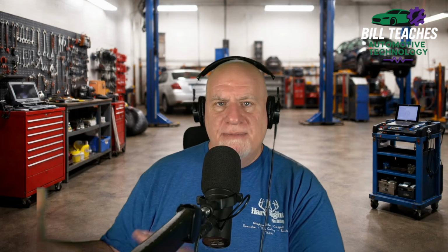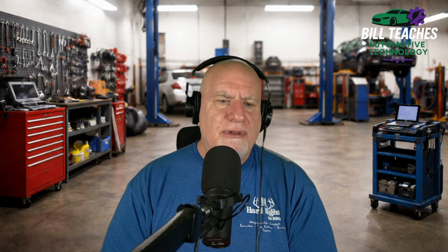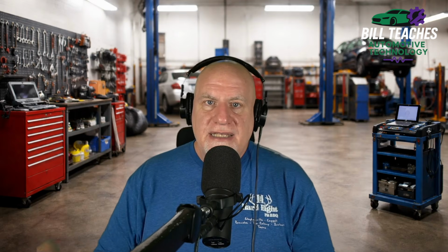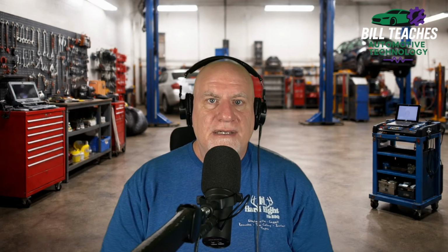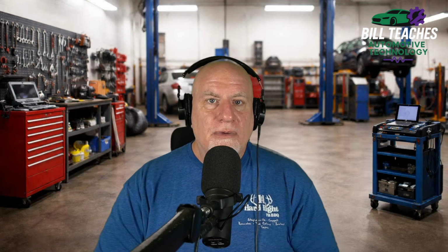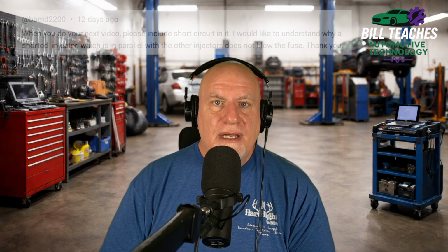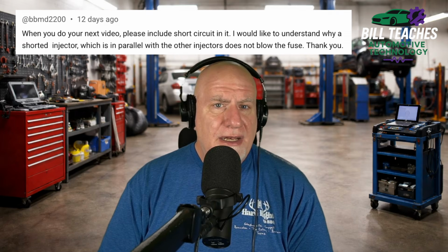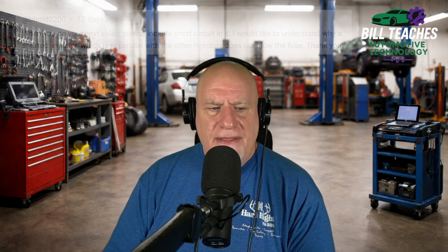But to help explain this, let's look at a simple injector circuit and walk through the different circuit failure possibilities. So today's lesson is going to be about opens, shorts to power, shorts to ground, and how a circuit normally operates. I had a viewer ask the question, why, when an electrical component like an injector fails, does it not blow the fuse? And that gave me the idea for this lesson.